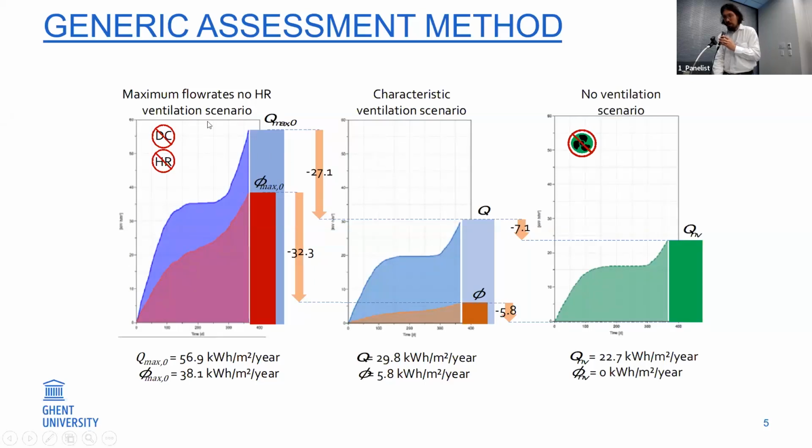Then we had another reference scenario that is a standard ventilation system without heat recovery and without demand control, that provides the required ventilation rates in all the spaces. And then we have the ventilation system that we're considering, either with demand control or heat recovery or both.